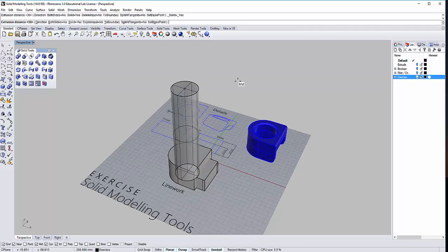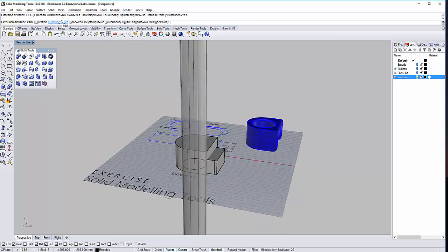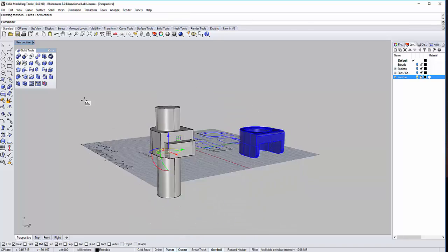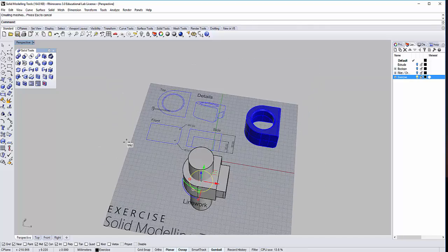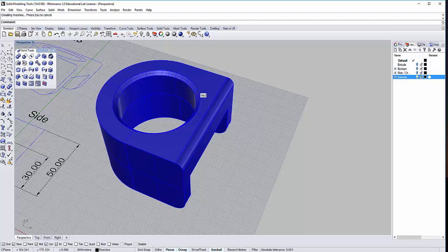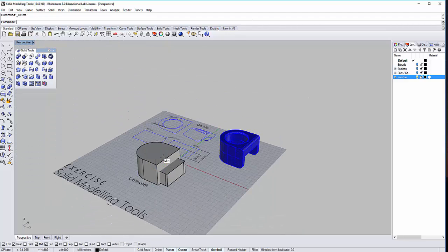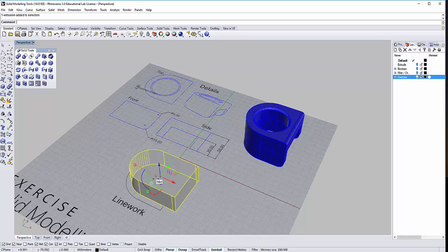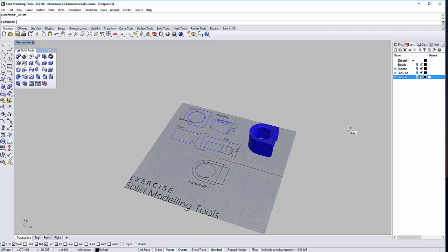I got my extrusion. Let's say for example I want to extrude both sides. I can also click this. Yeah, it will extrude both sides. So right now with this set of tools extruded, can I start to cut out the shape? And then I put the treatment on, chamfer and fillet. Right? Okay, I won't show you all the tools. I want you to try out the items. Alright. So once done, save. Make sure